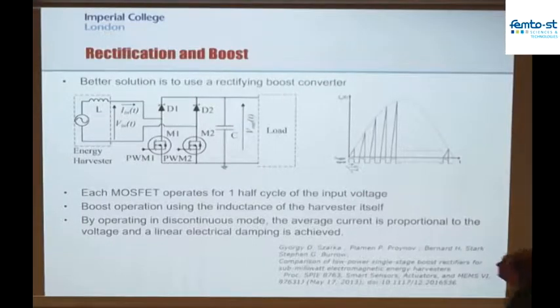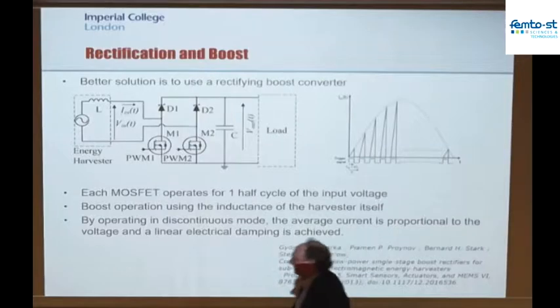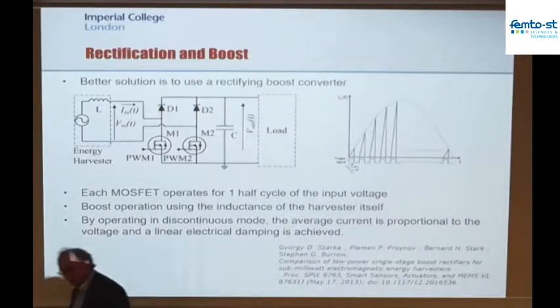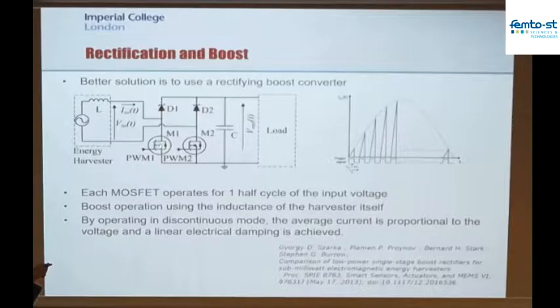This now, if you can see it, and it might take you a little bit of time after this lecture to look at this circuit, but this circuit now with the inductor, these two diodes and these two transistors actually is two of those boost converters that we just looked at. You can be able to see the first one quite easily. There's the transistor, there's the inductor, there's the input source, the diode and the output capacitor. So that there, that, and that is one of those boost converters.